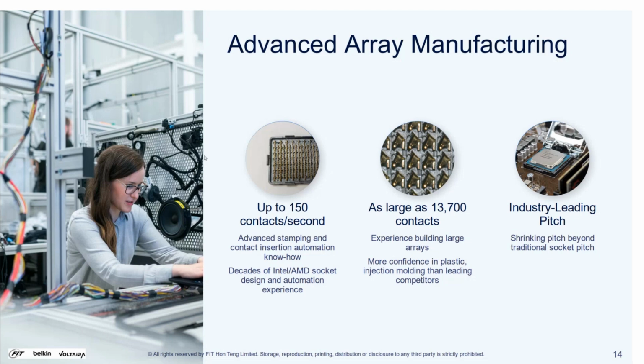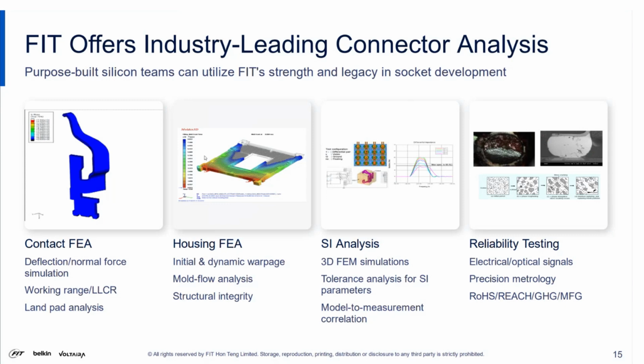We have increased confidence in the plastic and injection molding compared to our leading competitors. Industry leading pitch, shrinking pitch beyond the traditional socket. Like I said, the common trend right now is about the 0.9 range, but over the past decades, we have proven that we can produce sockets at 0.4 millimeter pitch. FIT offers industry-leading connector analysis. Purpose-built silicon teams can utilize FIT's strengths and legacy in socket development.